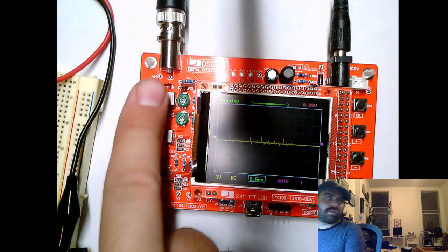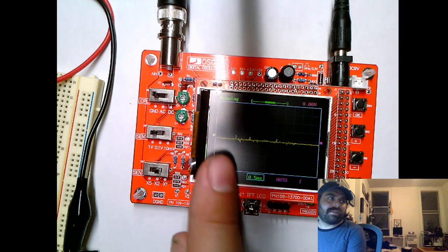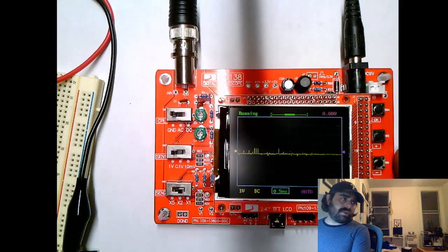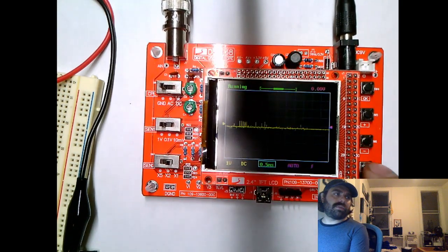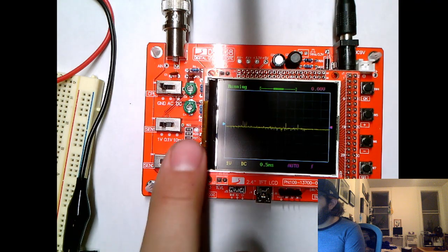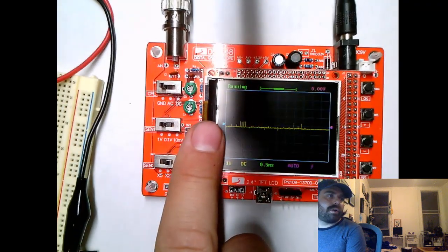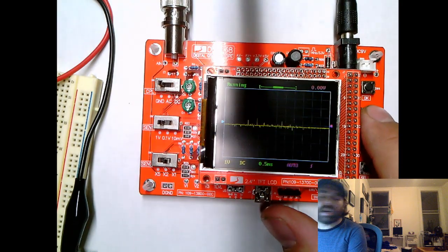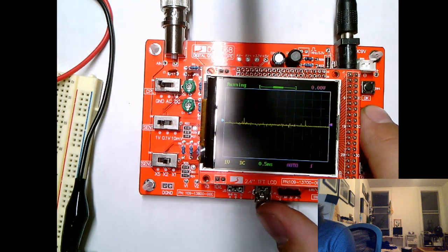However, if you switch to ground and your line is anywhere other than in the center, you might want to adjust that. So what I'm going to do that is I'm going to use this little button down here to select. This will kind of cycle me through different functions here. And eventually I'm going to light up this little arrow light blue. And then I can use the up and down arrows to kind of adjust where my line is, right?